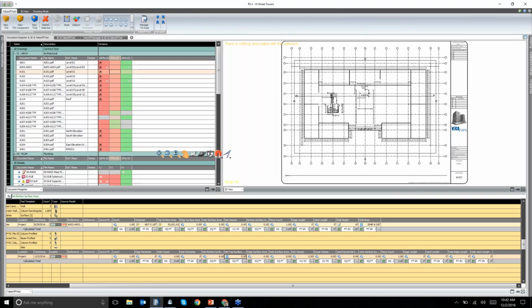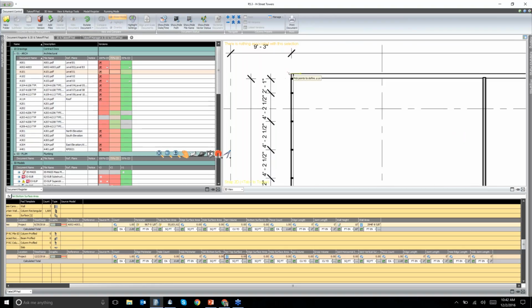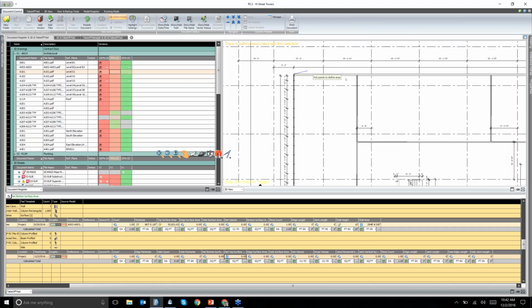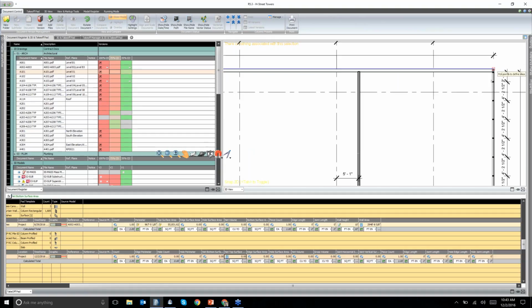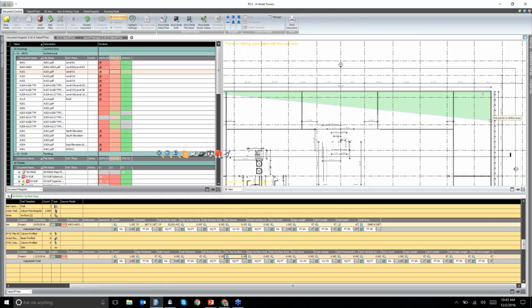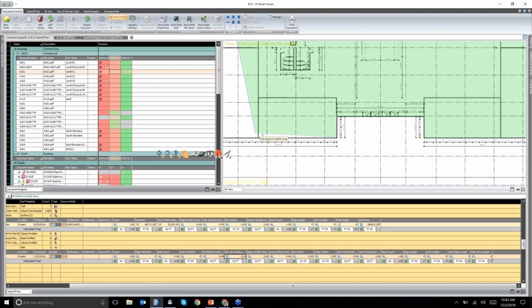As soon as I select that, I get some tools up here on my toolbar. I want to get an area, and I'm going to snap to points. So now I've just activated my takeoff tool, and now I can easily just snap to points. I'm just going to go around. Since we're snapping, we don't need to get super close. I know there's solutions out there that don't snap to lines. So this gives you a lot more accuracy and actually a lot more speed.